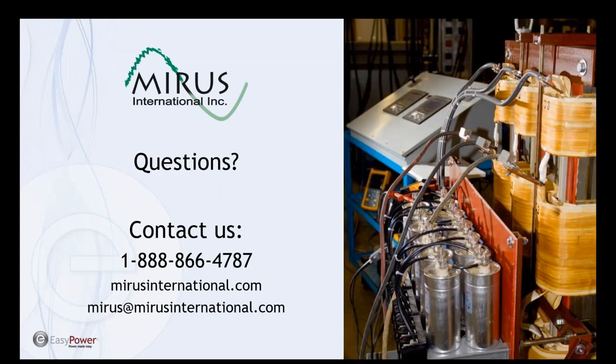clarify. The first question is about resonance, and they asked, what are the likely scenarios for resonance for cap bank installation? They mentioned that their facilities are tuned to the 4.7th harmonic, and they want you to elaborate perhaps on why we did tune below the 5th in order to prevent resonance with the 5th.